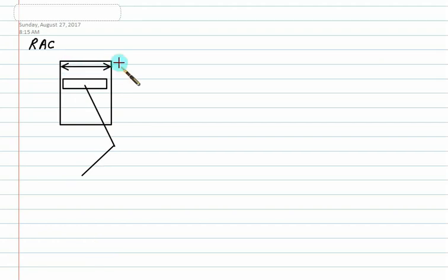Then this one is called the bore of the cylinder. This one is called the length of the cylinder. We represent them as D and L. D is called the diameter, L is called the stroke. So Vs is called the swept volume, given by pi by 4 D square multiplied by L. This is the theoretical displacement.